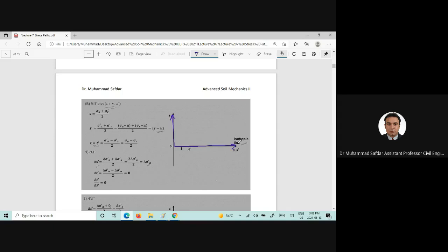In the isotropic line, for example, if we are plotting that as S prime and we are performing a consolidation test, so from the consolidation test we are starting with 0 horizontal and 0 vertical stresses, and if we are moving from this point till this point, we are having any confining pressure, what would be the value of K, or the lateral earth pressure coefficient?